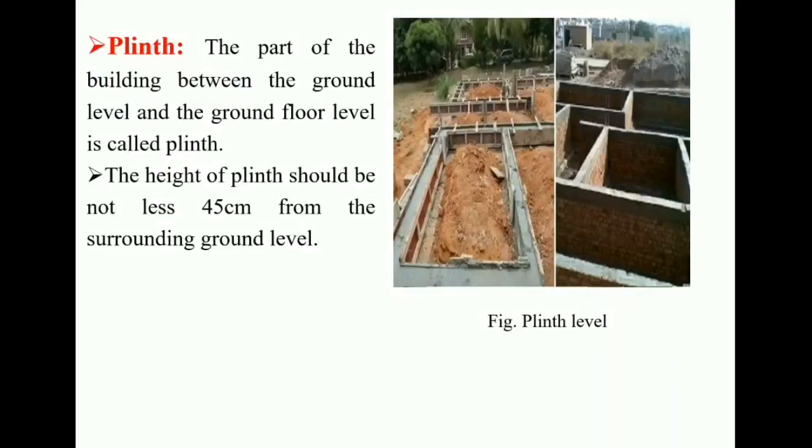So first is plinth. You can see in the figure, this is the plinth level. The part of building between the ground level and ground floor level is called plinth. A plinth is normally constructed just above the ground level and immediately after the foundation. It raises the floor above the ground level and thereby prevents surface water from entering the building.